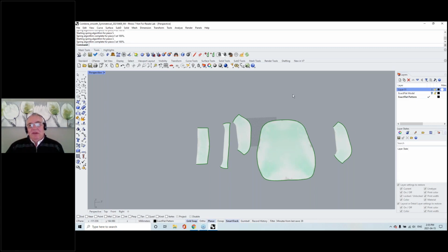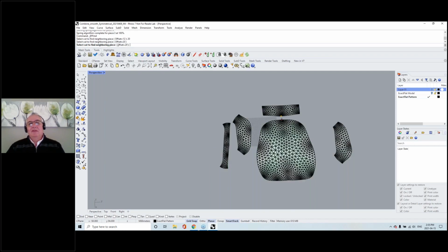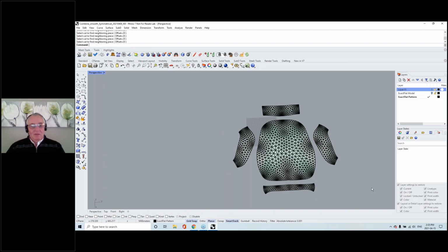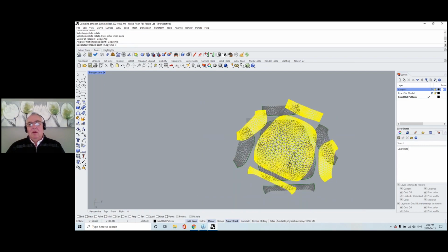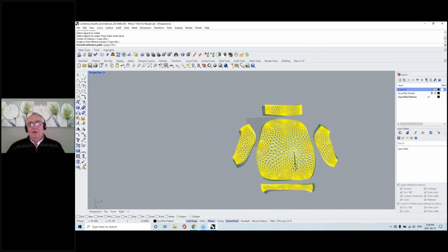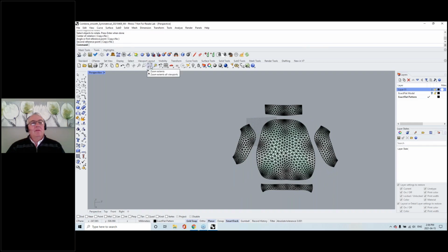So once we're here, the next thing I want to do is walk my pattern, and we have a tool called the Find tool, and it's this icon here that has binoculars, and I'm going to change this to 20, and that'll be my offset. So when I go around and I select a piece, it's actually going to find where these pieces get sewn together. So I'll set that all up. And then I'm just going to rotate this, so I'll select these pieces. Oops, I'll just straighten that out there and just move this over a little bit.